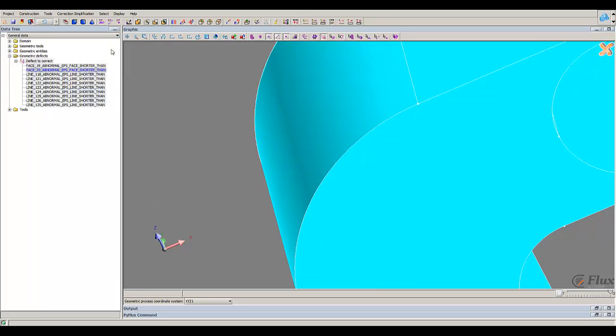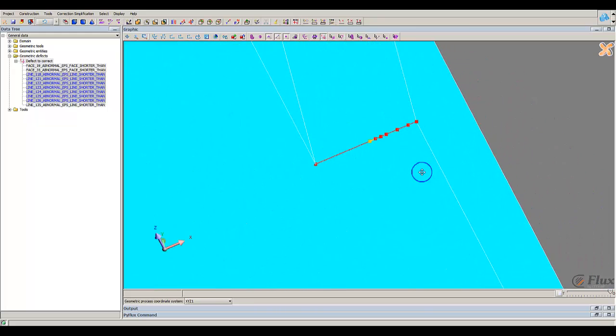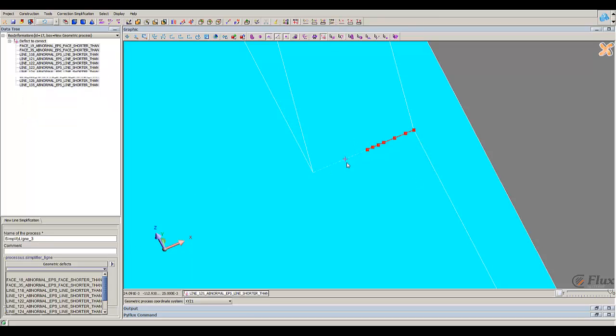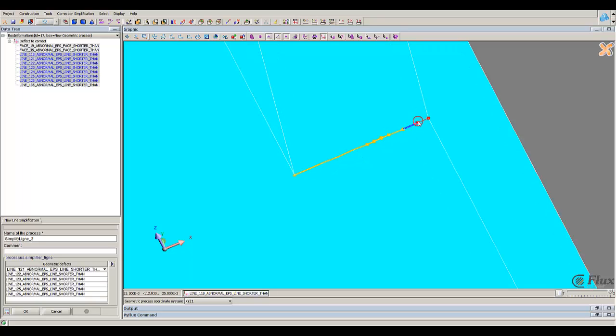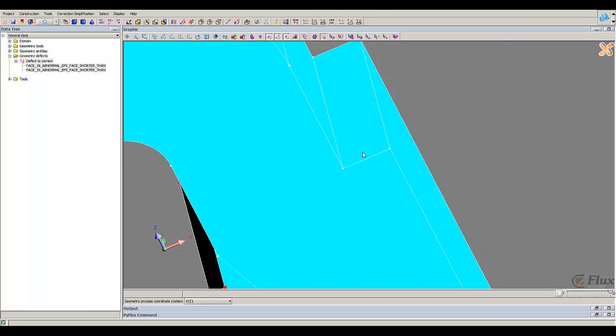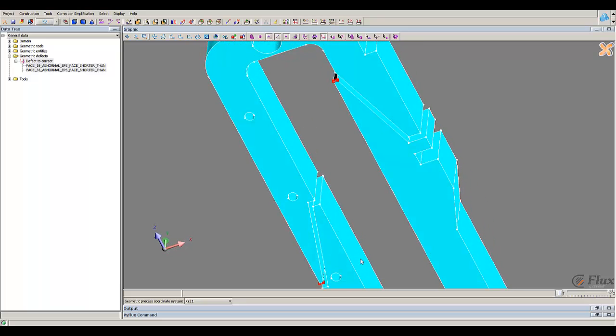We can detect one more time the lines. Okay, so we corrected it here. Now we can go on those lines here, and now I can simplify all the lines. I detect. Okay, so now I don't have any defects. I have only the two faces which are normal in this geometry. Now let's make a defeaturing of the geometry.